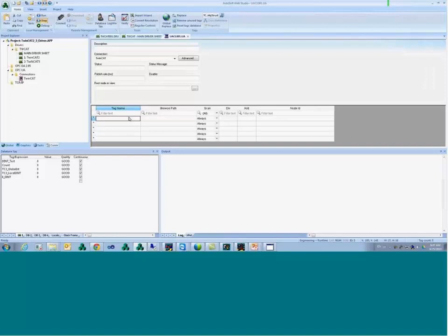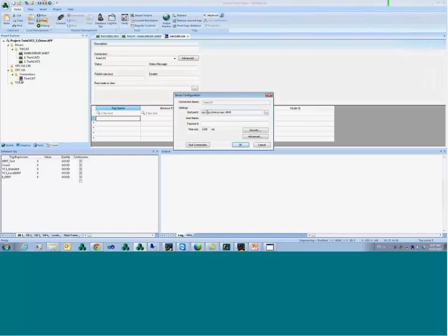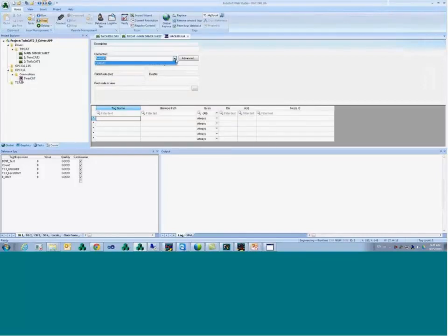Okay? I'm sure that the TwinCAT people would be able to help you configure the UA server much better than I could on their end. But once the UA server is running, that's pretty much what you do. You create a connection, okay? Give a name to the connection, select the connection on your worksheet, right-click, browse. It's going to fail, as you can see. And then you associate the item that you browse to the items here, to the Web Studio tags here. Okay? I'm really sorry I cannot demonstrate that, but that's the way you have to configure it. It's as simple as that.